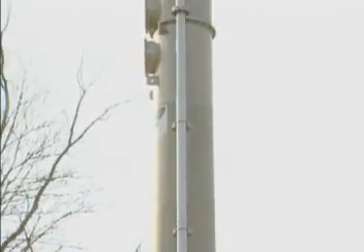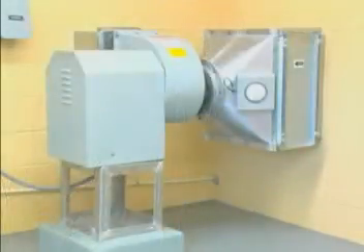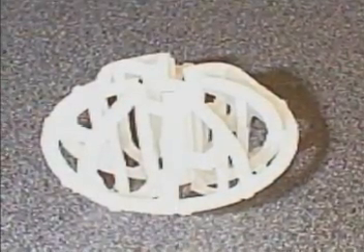Aeration towers can remove volatile gases like hydrogen sulfide. They can also be used to oxidize iron from the soluble state into an insoluble state. Aeration towers may simply infuse air into the water, or they may also contain devices designed to disperse the water particles, which makes the aeration more effective.